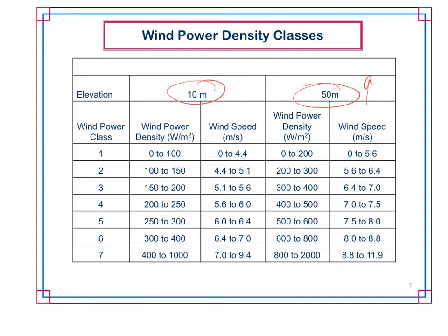So your turbine heights can be much, much lower offshore to get to those power levels that you're talking about. First off, the wind tends to be more higher speeds offshore, but that has a lot to do with the fact that there's less friction for the wind. So I'll use that term, and it's not 100% accurate to say friction, but it works pretty well.